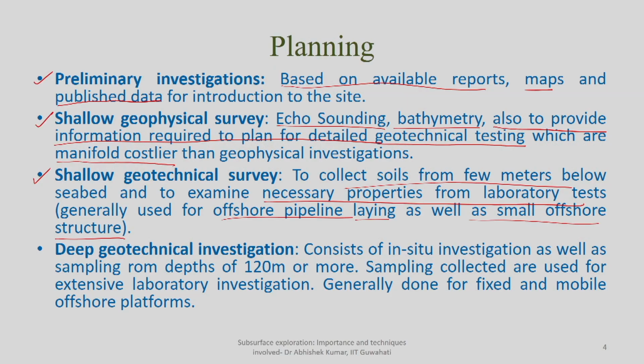Just collect the soil sample, determine its strength characteristics and soil properties from laboratory investigation, and then based on the obtained result you can go ahead with your execution part. Then comes deep geotechnical investigation, which is particularly used when we are going for maybe high load bearing structures, or maybe for exploration rigs, or maybe bridges can also be there which may require deep geotechnical investigations at the site.